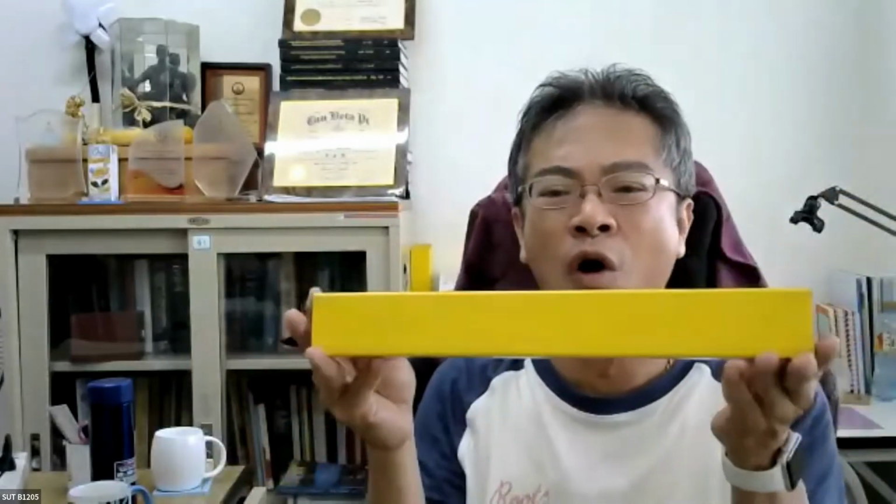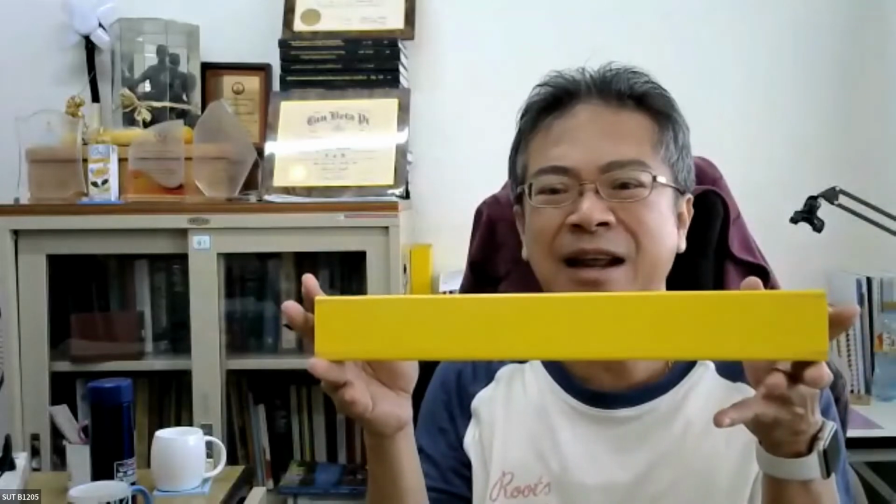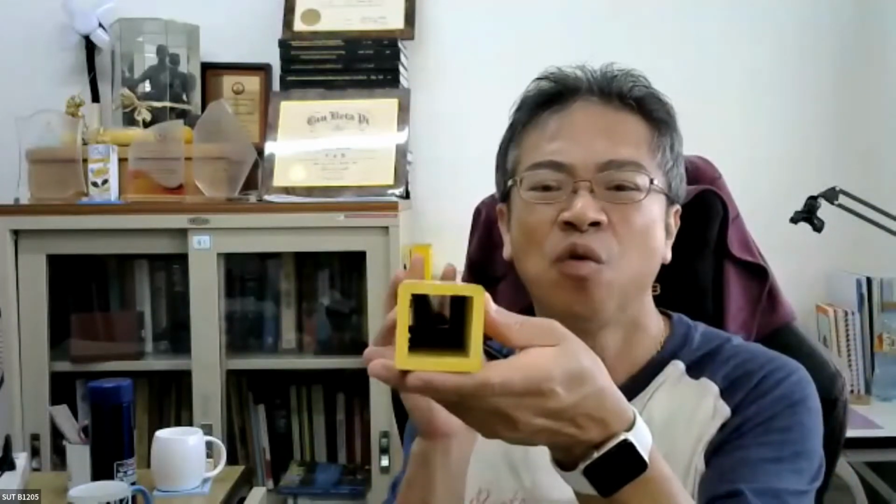This is an example. If we would like to determine the material property, we will cut a piece of specimen from this structural section and we test it. But if we are going to test the whole beam like this, with this kind of section, we call it a structural test, different from the material test.